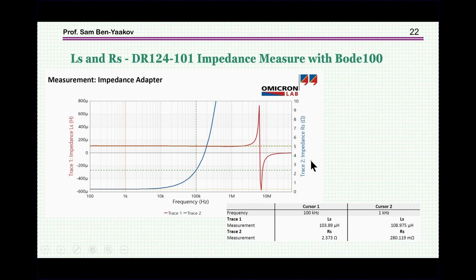This is the scale of the resistance. And obviously, if you have an appreciable ripple in the case of PWM, or if you work in a resonant converter and if the frequency is high, you are in big trouble. So without this information and assuming that everything is okay, you might get into real trouble if you ignore this aspect.